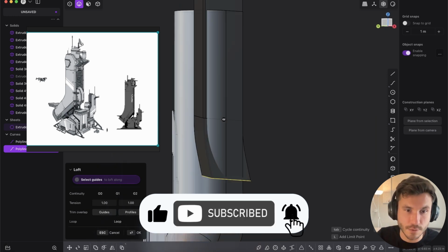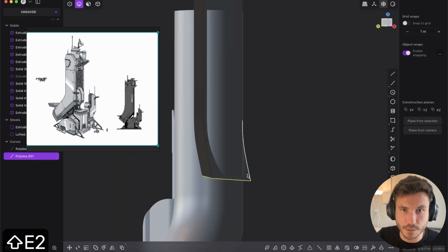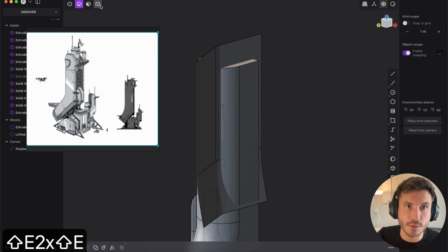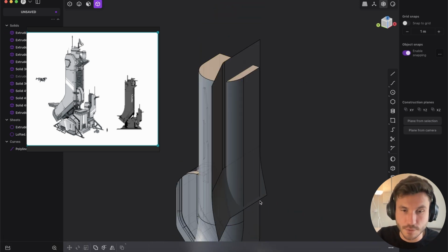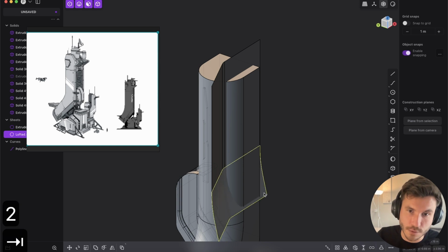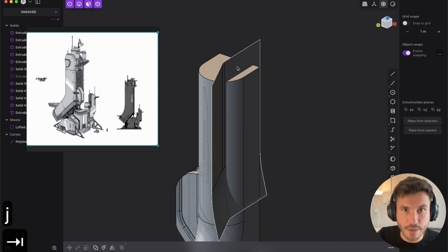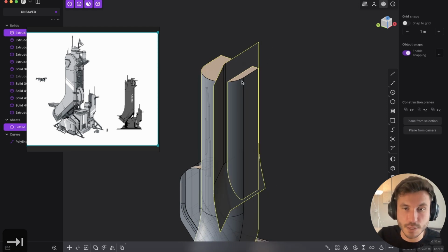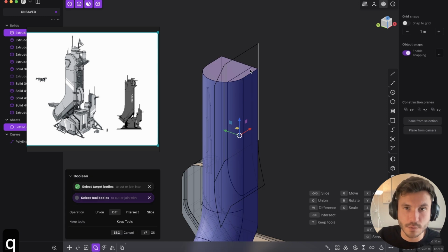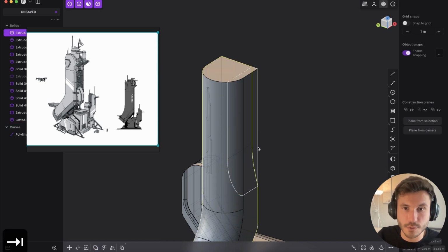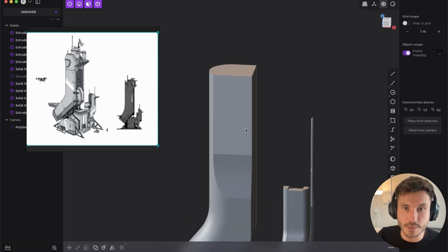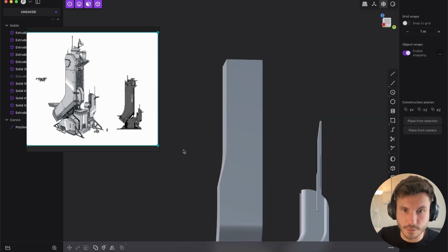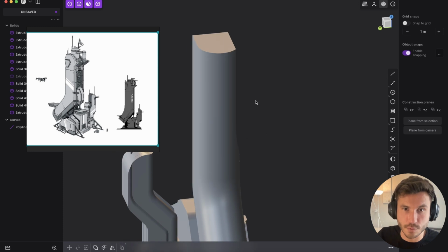Because if you press OK and delete this curve, and now in object mode, select this big piece and shift click this sheet. First of all, you have to connect the sheet. So select this sheet and this and join. And now select the big piece, shift click the sheet and Q to Boolean that, because now you can just delete this piece and you have this nice rounding. And that's cool.